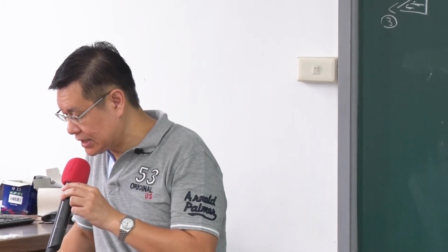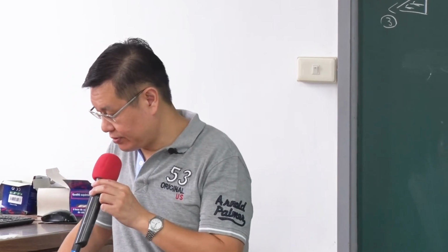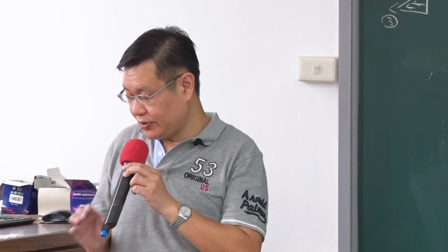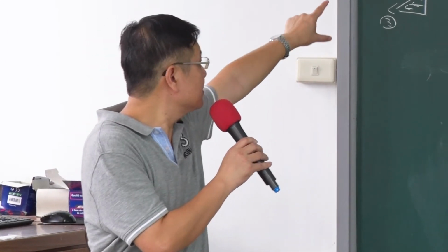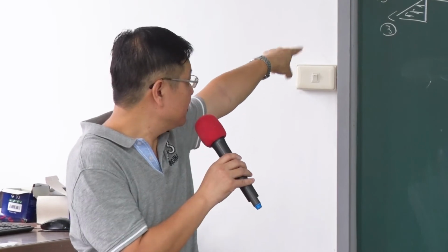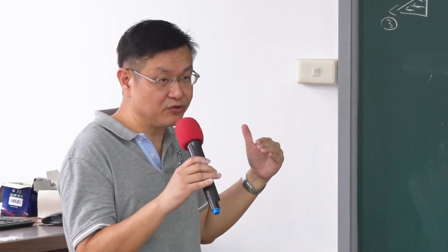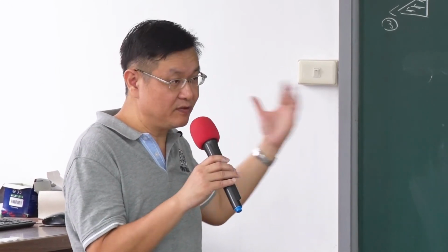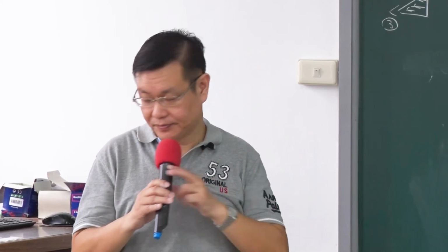We need to go back to the literature to find it out. But they have some differences, okay? So when you are choosing different types of material, you need to consider the position as well. Different positions give you a different sign, a different direction of the stress or strain, which can give a different value of the gauge factor. Okay.